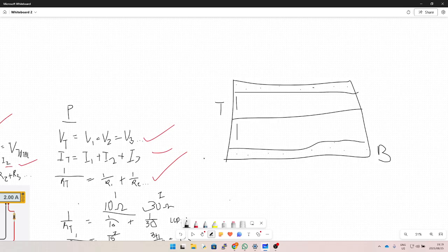Now, how it's connected is there's a small copper plate at the bottom. That's how you know it's connected. Now, what is a bus strip used for? Generally, you connect a 5-volt power rail to it and a ground here. It depends on what it's labeled, because it will be labeled positive and minus.